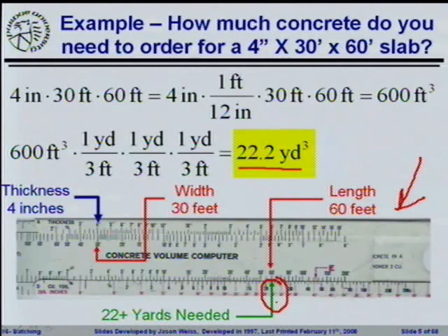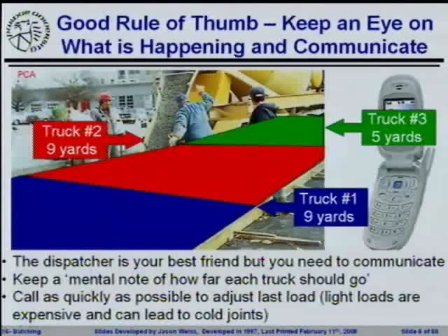This is something that was set up so that it's very easy to estimate the amount of concrete. Now, one thing that I will point out here is whether you do 4 inches, 3.75 inches, or 4.25 inches can make a big difference on the yield that that concrete is going to have and whether you fill up the forms. So there are a few things that you need to do when you're looking at this, and in such a small pour, this isn't such a big deal, and I apologize for bisecting this gentleman here with my